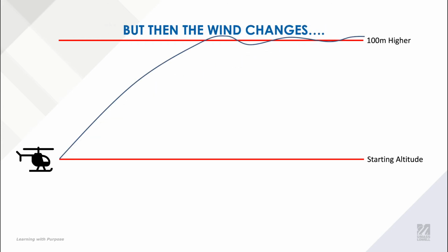So you could oscillate around your point, never quite reaching it. You could go unstable and start oscillating much more around it. After every iteration, you could end up maybe 5 meters higher, 10 meters lower. It's difficult to say. So clearly we need more than just one knob to tune in this. We can't just rely on the proportional control. There must be other gains we can set.